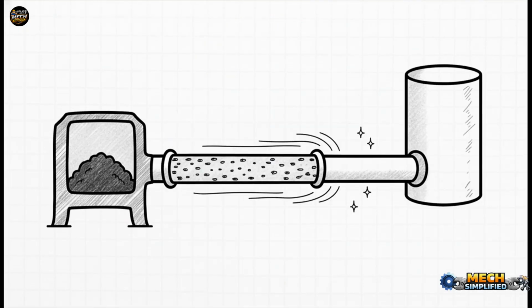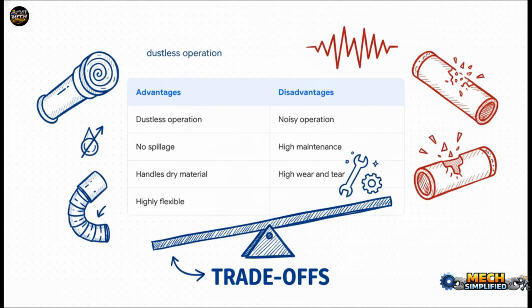Well, one of the coolest and most effective solutions is something called a pneumatic ash handling system. Forget about messy conveyor belts or sloshing water around. This system basically works like a giant, superpowered vacuum cleaner. It uses air to suck all that ash through a completely enclosed network of pipes and shoots it directly into a storage silo. And this, right here, is a perfect example of a core concept in all of engineering.